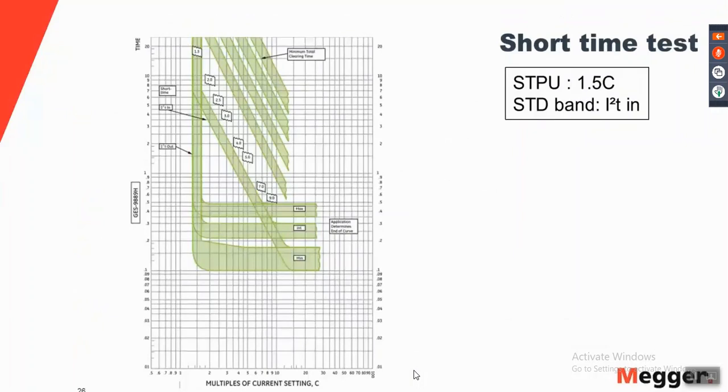So let's say we set the pickup value at 1.5 times the long time pickup. So 1.5 times C. The short time delay band is set at I square T in. If you look at the short time delay characteristics here, you'll see that there are two responses. There's I square T in and I square T out. What I square T in means is that the trip time is dependent on the magnitude of the current. So higher the current, lower the trip time. As you can see, the band has a slope.